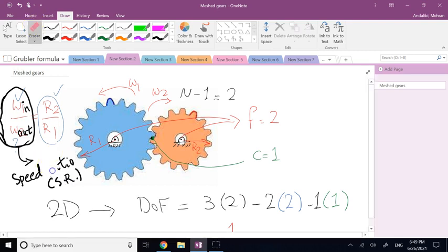And that's the most important thing in a gear train, a gearbox, the speed ratio. When you're driving a manual car and you put your car transmission in low gear or high gear, all you're doing is changing these input output sets and changing this ratio R2 to R1, and so you're getting different speed ratios.